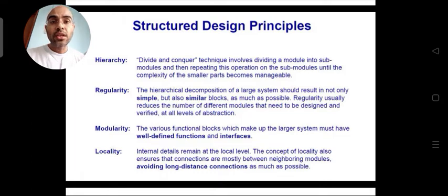Then there will be a lot of interference between these two gates and the other gates. So this should not be there. If two logical gates are interacting too frequently with each other, they should be placed together. Similarly, if two bigger submodules are interacting with each other frequently, they should be placed together. That is what is meant by locality.